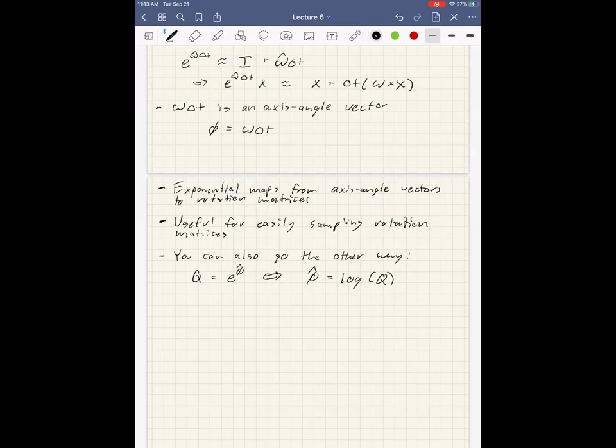So yeah, there are some quirks, but practically speaking, this is the right thing to do on a computer if you need to sample rotations, and you don't generally worry about the tails with vanishingly small probability. If your covariance is like pi, then it gets weird. If your covariance is reasonable, like 5, 10, 15, 20 degrees, what you would see in a robotics application, it's totally fine.